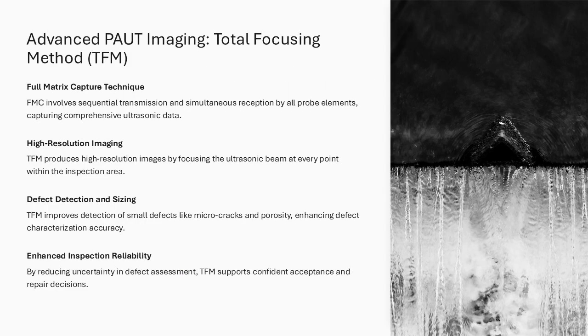The total focusing method, TFM, represents a significant advancement in ultrasonic imaging and is increasingly applied to complex cladding inspections. TFM is based on full matrix capture, FMC, where each probe element transmits sequentially while all elements receive, resulting in a complete dataset of ultrasonic responses. Advanced algorithms then focus the ultrasonic beam at every point within the region of interest, producing high-resolution images that approach